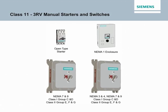Siemens Class 11 across-the-line manual starters and switches provide control for machinery where motor start and stop control is not required. Class 11 3RV manual starters are used for single-phase and 3-phase motors up to 20 horsepower at 575 volts and have bimetallic heater elements that provide Class 10 overload protection. These starters have ambient temperature compensation. A built-in differential trip bar reduces tripping time in the event of a phase loss condition.